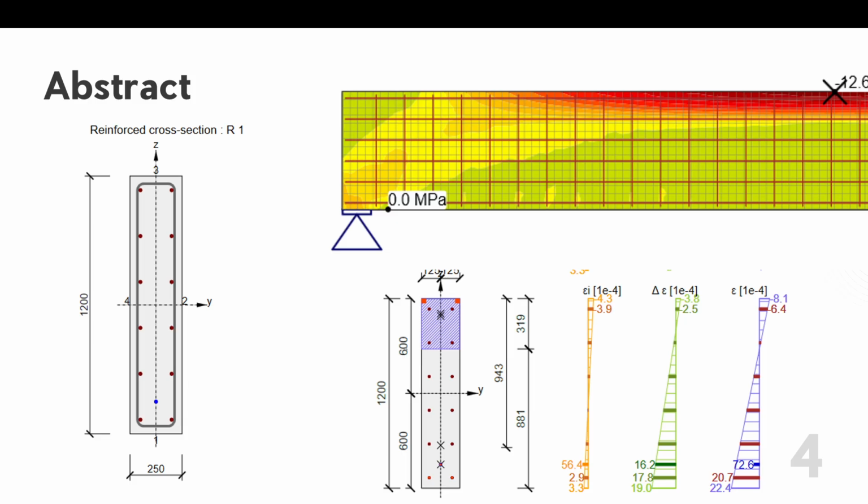There is a perfect bond between the steel and the concrete, and concrete carries no tension for the ultimate limit state. You give it the internal forces at the section, coming from a linear model calculated in some finite element software, and it returns the stresses and strains. Tension stiffening only enters the crack width calculation. That is not the point of this presentation, because we are verifying the ultimate limit state.